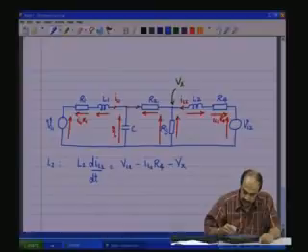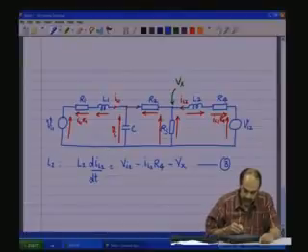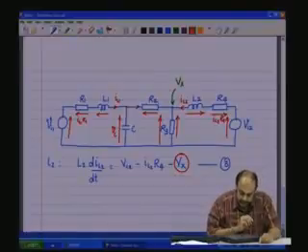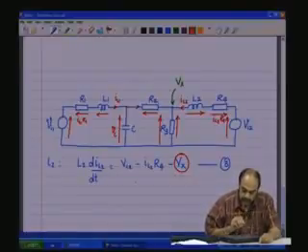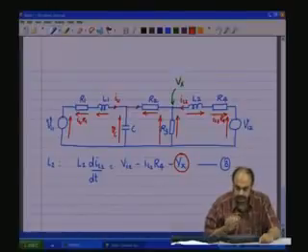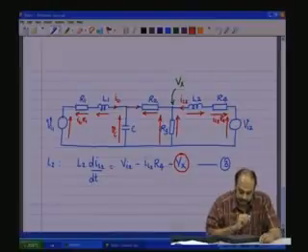And the third equation is this, which is revolving around the dynamic element L2, which is L2 diL2 by dt equal to Vi2 minus IL2 R4 minus Vx, and Vx again is the intermediate variable, which is expressed as before. So, all three equations are expressed as functions of input variables and state variables only, the intermediate variable being expressible in the form of state variables.